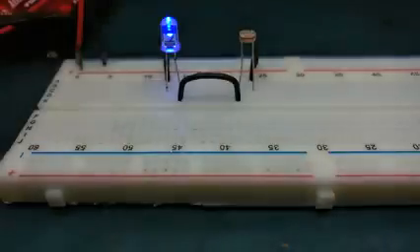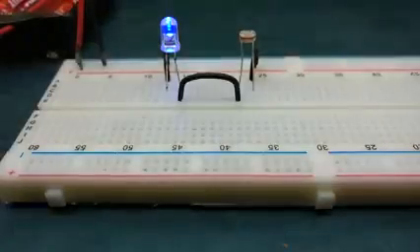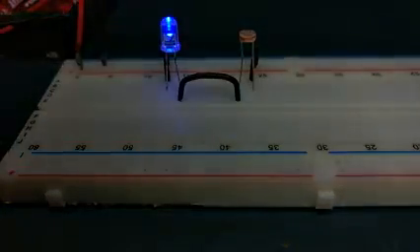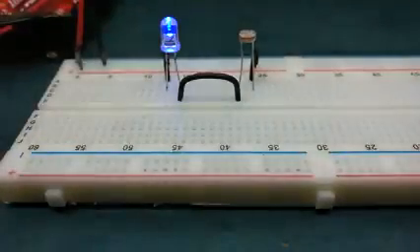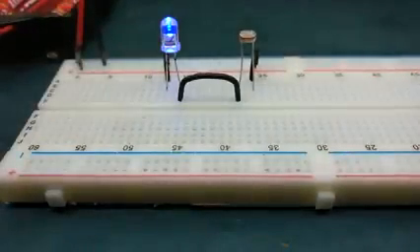This is a basic light sensor circuit you can start with, but it has some limitations like you can't control at what brightness of light the LED turns on or off. Also, practically we would want the LED to turn on when it is dark and turn off when there is enough light. This circuit can't drive heavy loads too. So for these reasons, we'll make a more functional circuit using transistors.